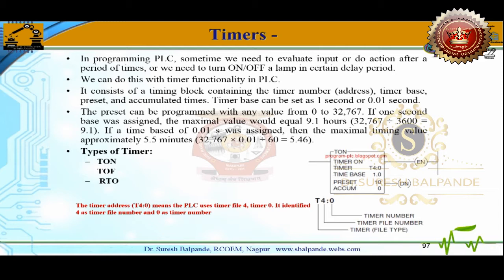In case of timer, we'll first try to understand the template, or the format, available for the timer. And there are three types of timer. One is called TON, second is TOF. So please remember, it's not TOFF, only TOF.